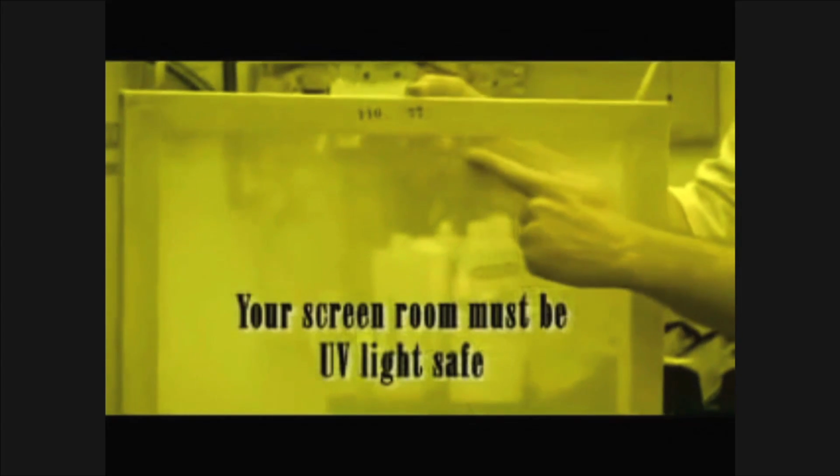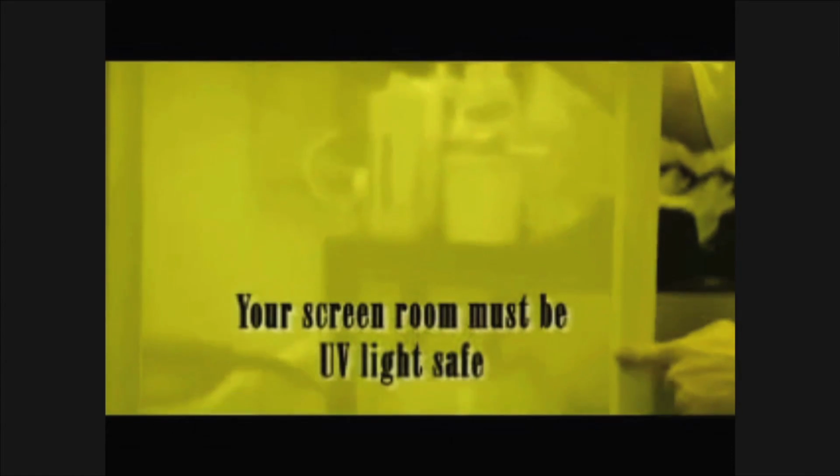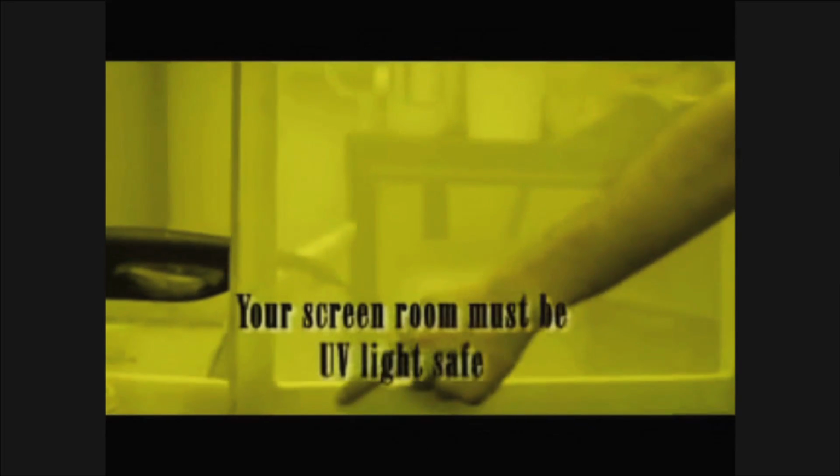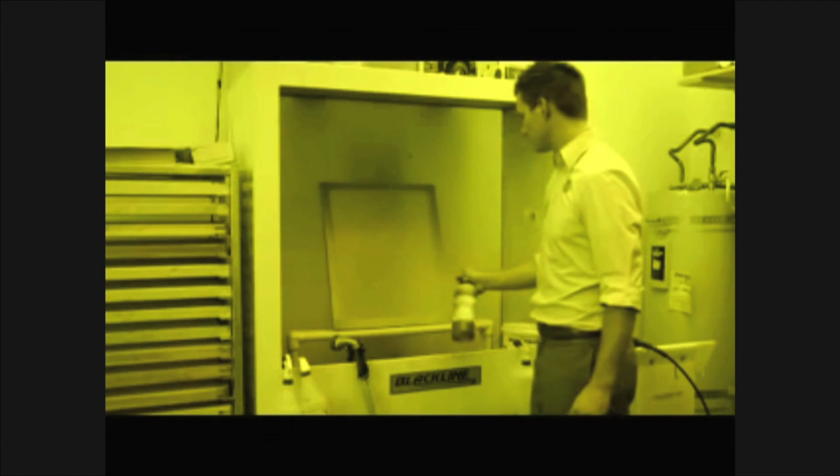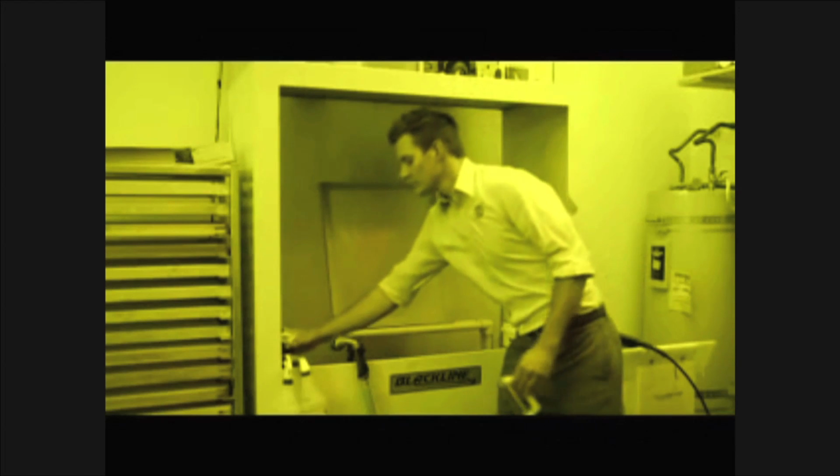Next up in the screen printing process is screen preparation and exposure. Screens come with either wood or metal frames. The mesh of the screen material varies depending on the type of job you are doing. Before you can coat and expose a screen, you must degrease the screen. This is a critical step in the process as it cleans all the contaminants off the screen so the emulsion will properly bond to the screen.